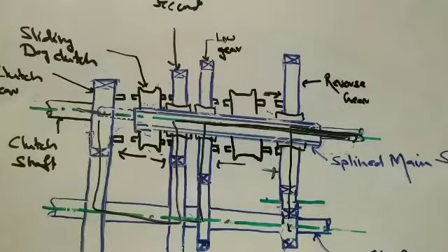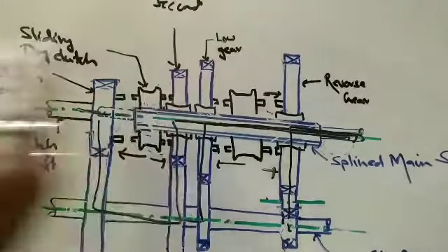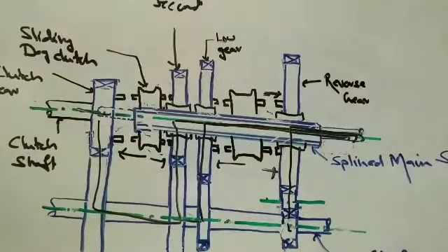So here all the gears are engaged, but the mechanism moves by the shifting of the dog clutch. So the wear is reduced, and we could go for the option of the helical gear, which is much quieter in comparison to the spur gear. And the second one is that as all the gears are enmeshed, the engagement and disengagement of the teeth every time causes damage to the teeth surface. So this does not occur because all the gears are in constant mesh.